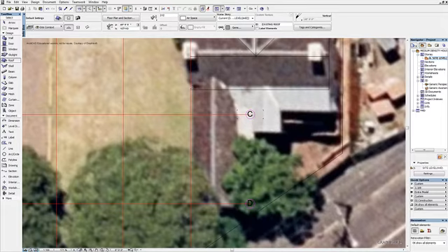Now, remember, the rule when you draw a roof element in ArchiCAD is that before you draw the shape, you must draw the pitching line or the pivot line, which runs at the base of the roof plane, and you need to indicate to ArchiCAD in which direction the roof will incline from the base pivot line that you draw.